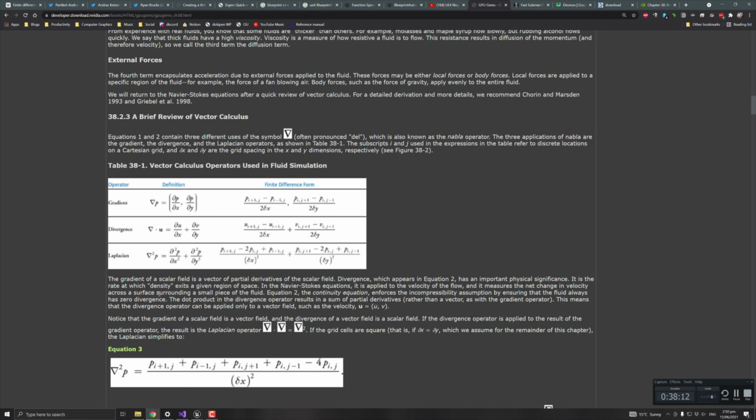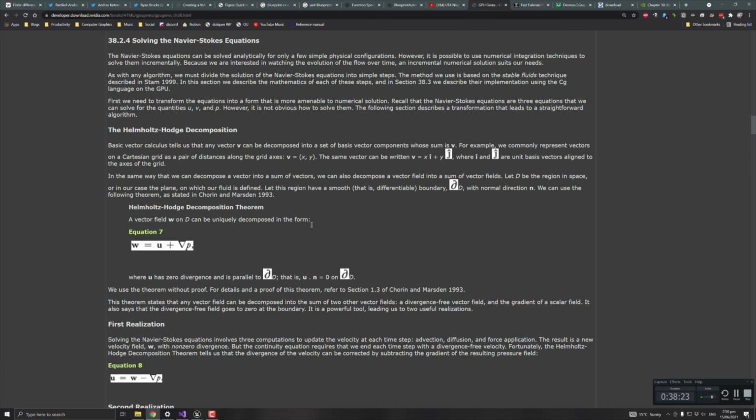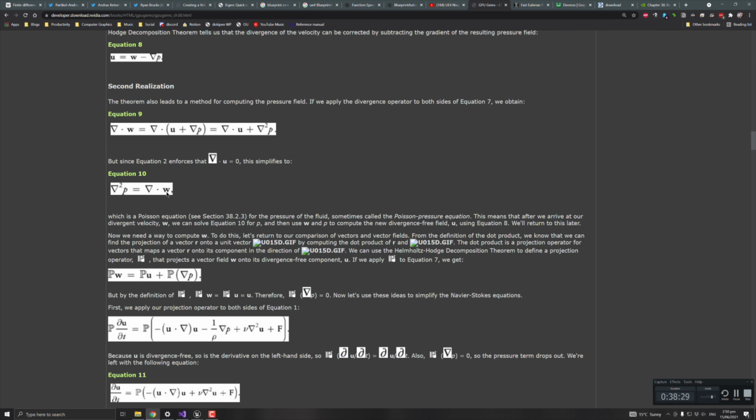But with this pressure field, we don't know how to do that in an intuitive way up front, because you could technically create a P for a voxel by solving some equation locally, but that wouldn't necessarily make it the right P for the next neighboring voxel. You can go and correct that one, but then the one next to that isn't going to be right. So you've got this game of whack-a-mole where you're trying to come up with all these guesses for P that don't really make sense globally. They all have to be the right P for the whole system, for every single voxel.